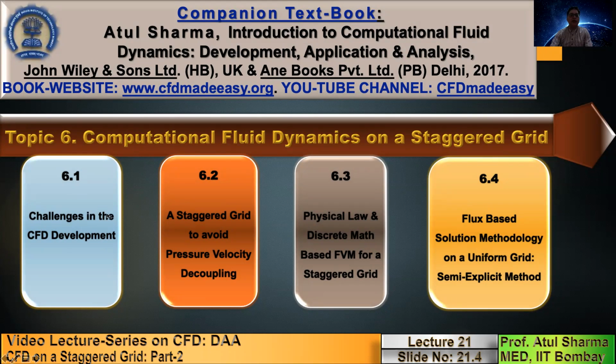I started with challenges in CFD development, where I mentioned 3 different challenges at the beginning of CFD development. The first corresponds to non-linearity in the advection terms of the Navier-Stokes equation. The second was that there is no explicit equation for pressure. And the third, there is an issue of pressure velocity decoupling when people started solving the Navier-Stokes equations. So these were the 3 challenges encountered in the beginning of CFD development.